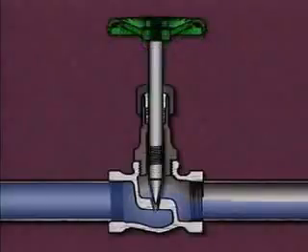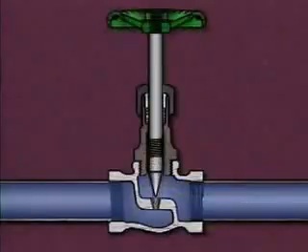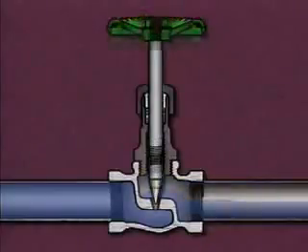A small movement of the valve stem causes a small, gradual change in the flow rate through the valve, which makes the valve capable of precision throttling. So needle valves are often used when precise regulation of flow is needed.